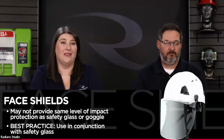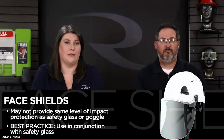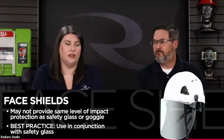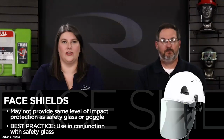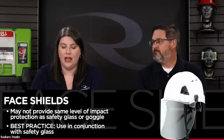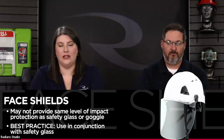face shields, depending on the type of material that they are made of, may not offer impact protection. Most of the time, if you're using a face shield, you'll see the use of a safety glass or goggle underneath it. And that's the primary reason why, because you're still needing that impact protection in that environment. So what are those materials? A PETG material is going to be one of your more economical options.